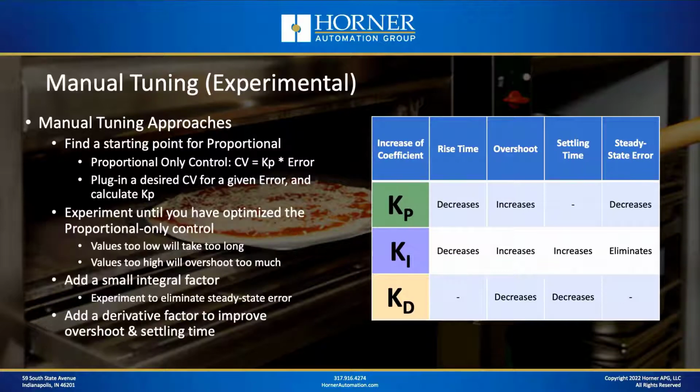Now, once you've plugged in some sort of term, whether you've calculated or you're just plugging it in off the top, you need to let that run and you need to find out if it's going to work for you. And of course, you're going to need to increase it if things are taking too long to get to the set point. You'll need to decrease it if you're overshooting way too much. But anyway, at some point, you'll have dialed in relatively well your KP term.